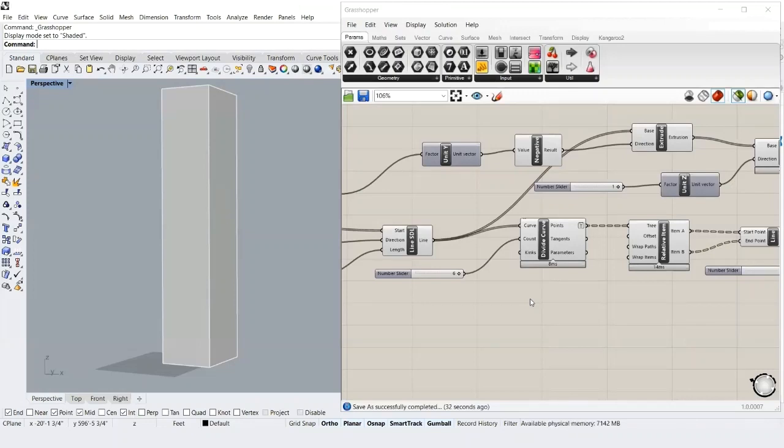Next, we are going to make a connection between the Rhino file and the Grasshopper code. Create a line in Rhino. Click vertical. Start it at the end point at the bottom of the base. End it at the end point at the top of the base.